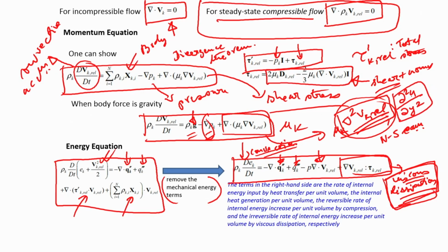If this distance is very small and the change of velocity is high, you can generate a lot of shear. If you generate a lot of shear, your viscous dissipation can be a lot higher as well. So, the work done by viscous dissipation can be high. This can become a formidable component, as the example I showed you with my finger, but do not try this experiment, you will actually burn your finger.